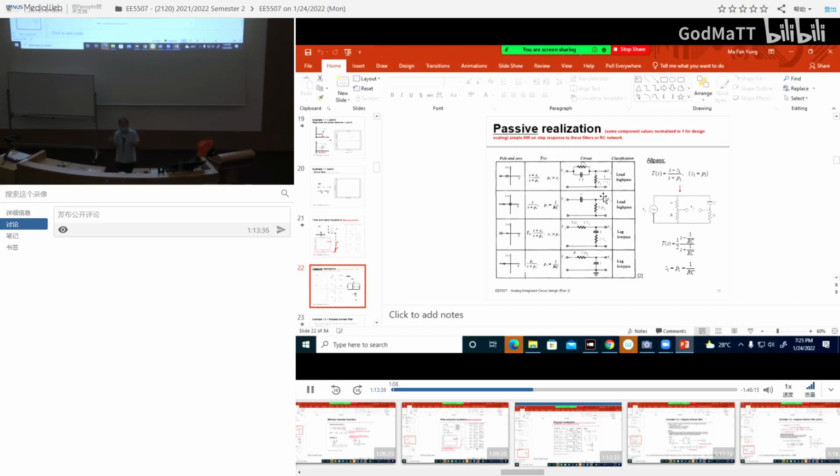So you cannot build very high efficiency inductors. That's the basic reason. Up to today, people cannot build high quality inductors using IC technology, because fundamentally your IC is 2D. Although the latest transistor is not really 2D, the FinFET actually is coming up.